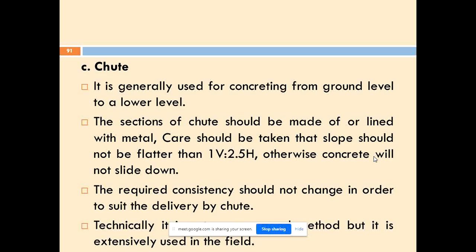If you use a pneumatic tire wheelbarrow, then it is good for concrete because it will not tend to segregate. If you are using a wheelbarrow without any rubber tires, then whatever homogeneity was obtained in the mixing will be completely lost.